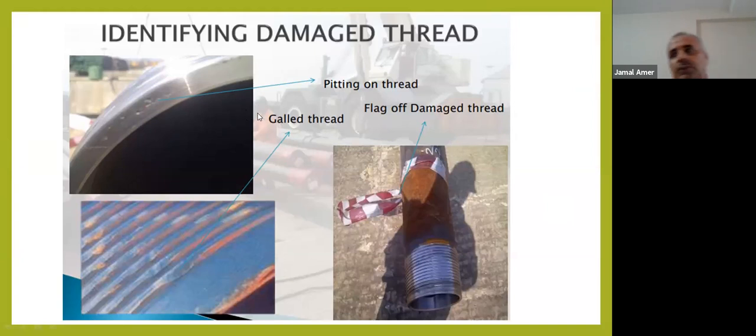Many wells now face what we call SCP, sustained casing pressure. Sustained means that even if we bleed off the pressure from annulus A, annulus B or annulus C, the pressure will return to the previous value it had before we bled off.